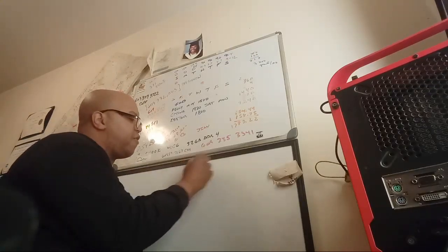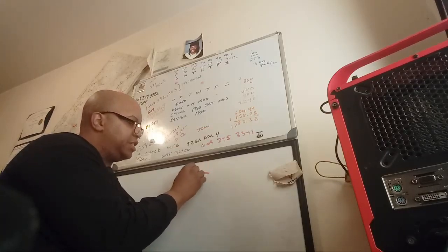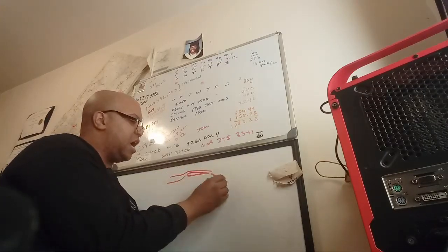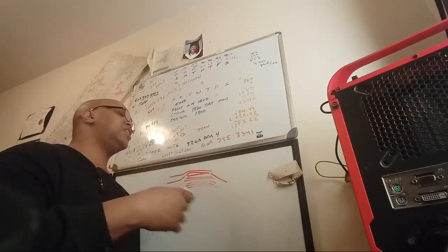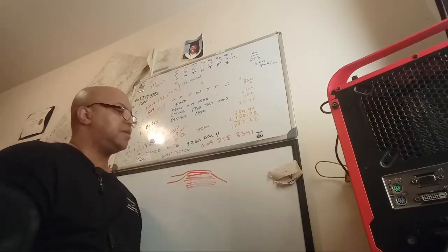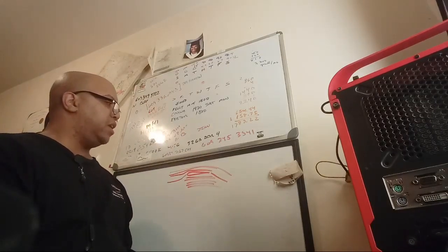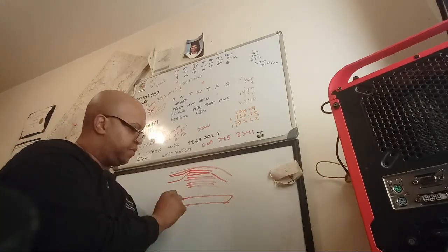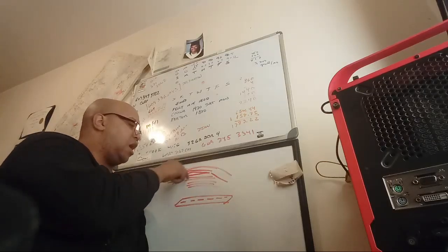So let's say our airfoil is at 2,000 feet. It's just flying and we're getting the laminar airflow we want. But we have to understand there's a natural upwash and downwash because we have all this air below the wing. Nothing is really disturbing the airflow around the wing. So we have our normal upwash and downwash. Now, when we get within one wingspan, typically around runways, the Earth is going to interfere with this normal upwash and downwash pattern.